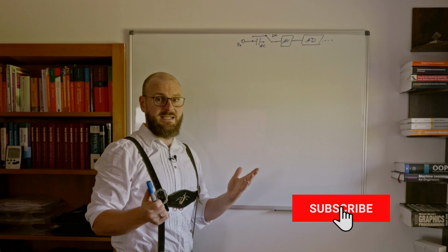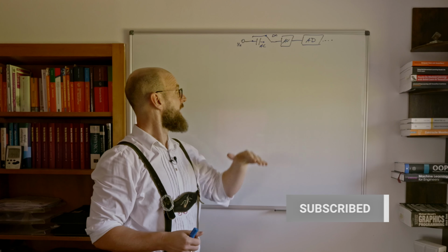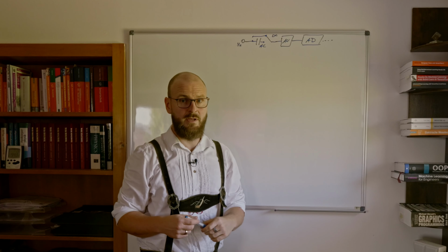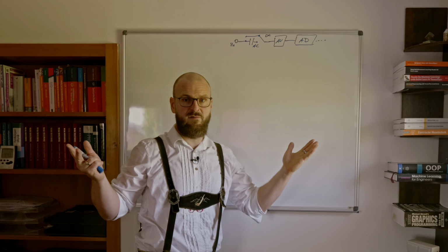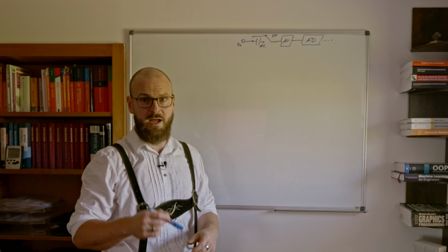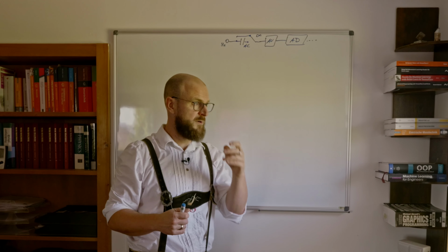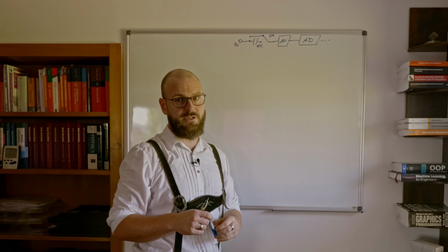Okay, what is that adaption unit about? It's about stepping down input voltages which are too high. Meaning when there's an input of some 100 volts, we can only convert up to 1 volt. We have to divide that voltage into a voltage which can be consumed by our analog digital converter.